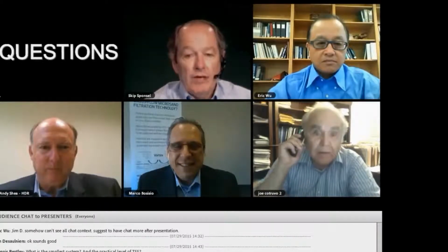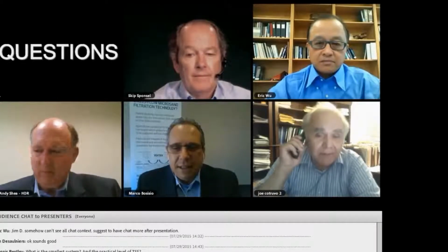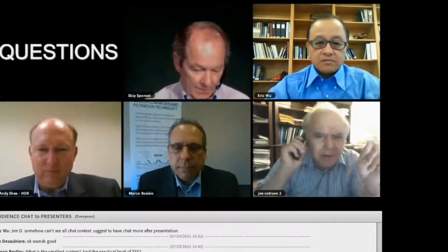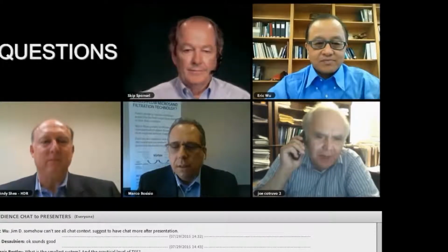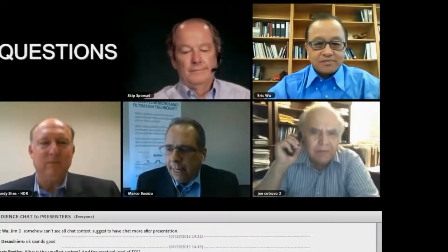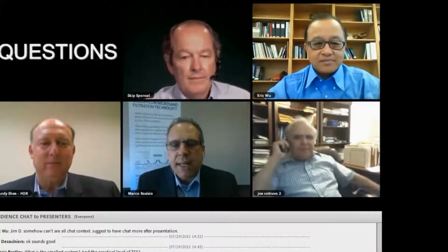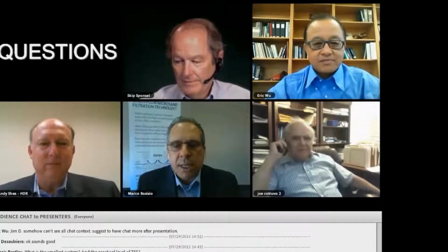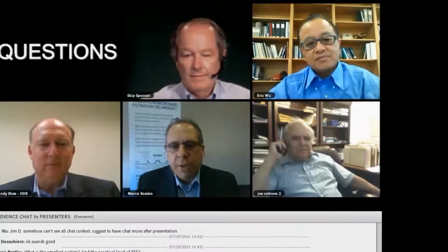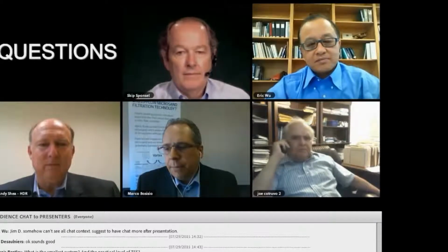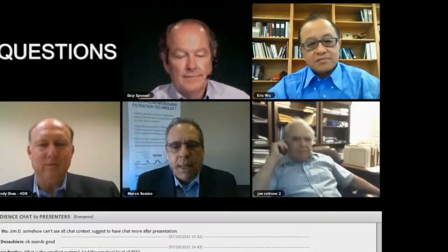Joe, do you have one? Yeah, I thought that was very interesting. Just two quick questions. One, is the sand really smaller than typical sand? Is it really microsand, or is that a trade name? And secondly, does it have any applications in drinking water for turbidity removal from a surface water? Okay. Well, thank you, Joe, for your questions. In the water industry, when we talk about microsand in general, there are other applications that use microsand. As you probably know, some clarifiers do that. It's typically understood that microsand is 150 micron and less, and our system uses 150 micron right now.